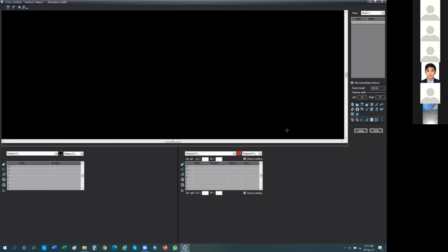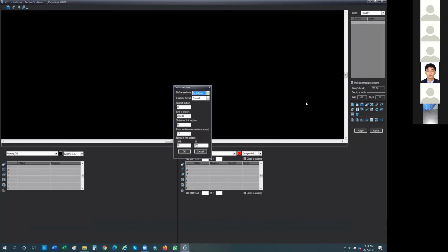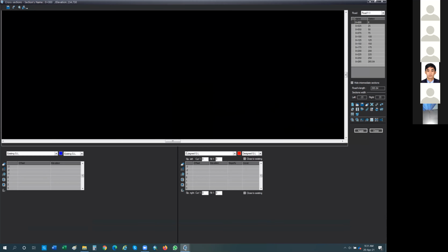Good, excellent. Now, first of all, you define the cross section. You press the define section button on the right. Now, upper left in this, where you are. Yeah, exactly. And press OK. You don't want to change anything. Good. So you have your list.